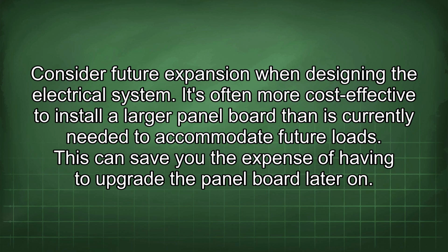Consider future expansion when designing the electrical system. It's often more cost-effective to install a larger panel board than is currently needed to accommodate future loads. This can save you the expense of having to upgrade the panel board later on.